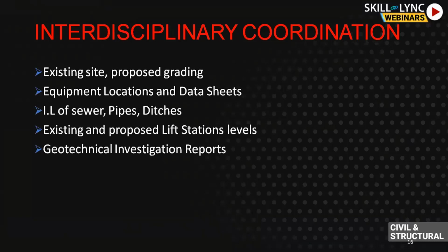And any level change will destroy the whole septic tank, sewage treatment plant concept. It will not work. Most of the plants are working from gravity. So you need to know what is the level of pipes and ditches there. Sometimes if there is no big area available for the sewage treatment plant, we will make some lift station with a holding tank. At that time, you will be requiring levels for demonstration.